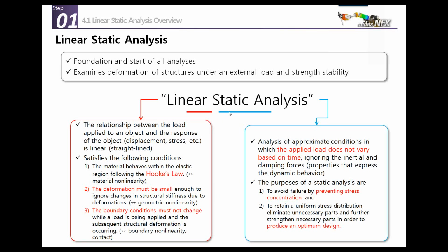Now the second part, static analysis. Static means that the applied load does not vary based on time, so it is independent of time. It ignores the inertial and damping forces, and the purpose of static analysis is to avoid failure by preventing stress concentration, and to retain a uniform stress distribution by eliminating unnecessary parts and further strengthening necessary parts in order to produce the optimum design.